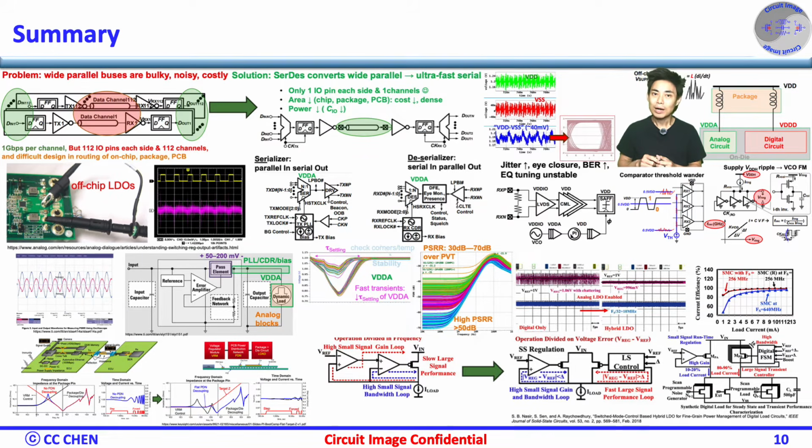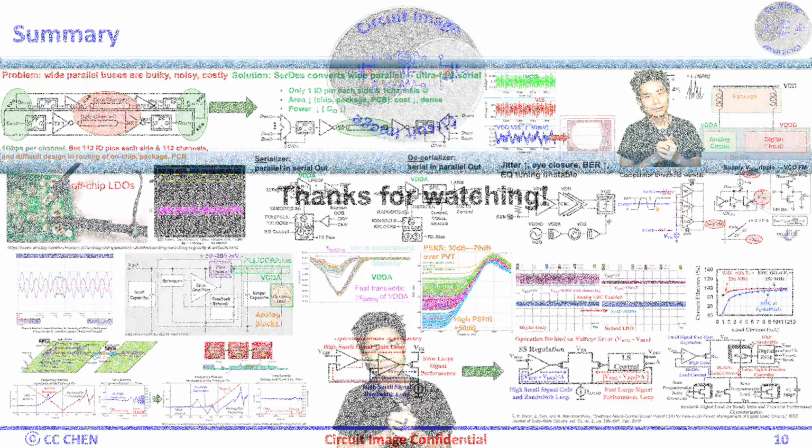A tiny milliwatt cost for massive gain in signal integrity. The next step in any design should be to specify this PSRR and noise target. Plan the layout and decoupling carefully and prepare for rigorous supply injection tests to validate the final design.